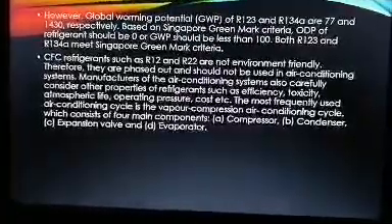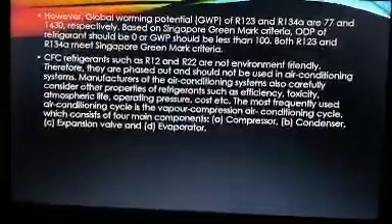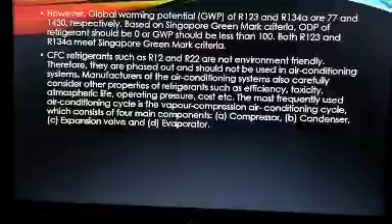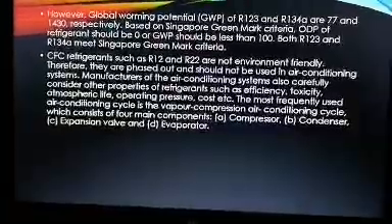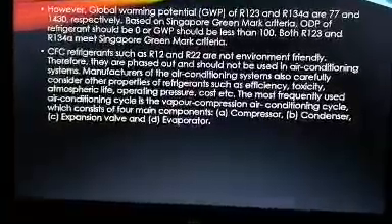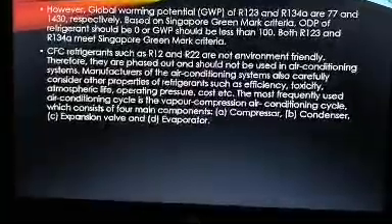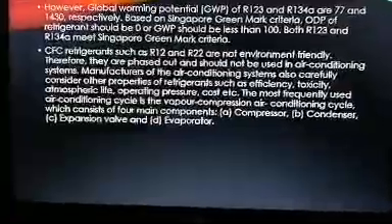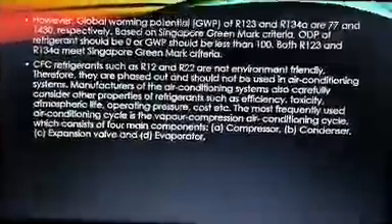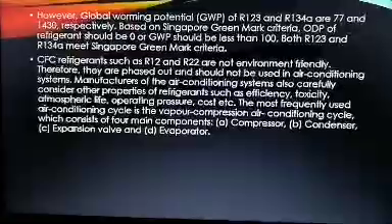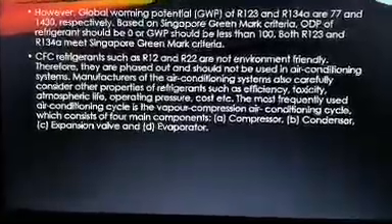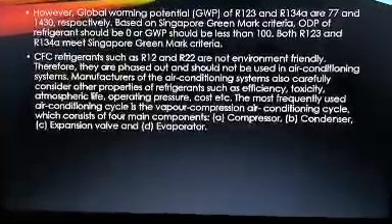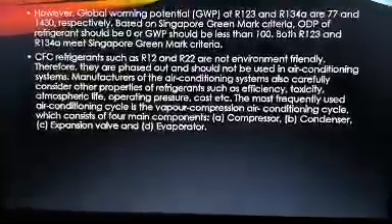CFC refrigerants such as R12 and R22 are not environment friendly. Therefore, they are phased out and should not be used in air conditioning system. Manufacturers of the air conditioning system also carefully consider other properties of refrigerants such as efficiency, toxicity, atmospheric life, operating pressure, cost, and etc. The most frequently used air conditioning cycle is the vapor compression air conditioning cycle, which consists